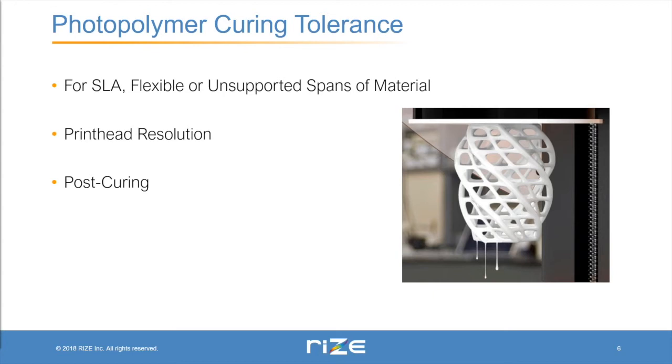Some of the challenges are that if you have portions of it that don't have supports attached to them, then it's more likely that those portions will bend as the part gets printed and weight is applied to them. And there are also some photopolymer materials that come out more flexible than rigid, and those can also succumb to some bending as they build, which will produce warped geometries and not quite what was specified.